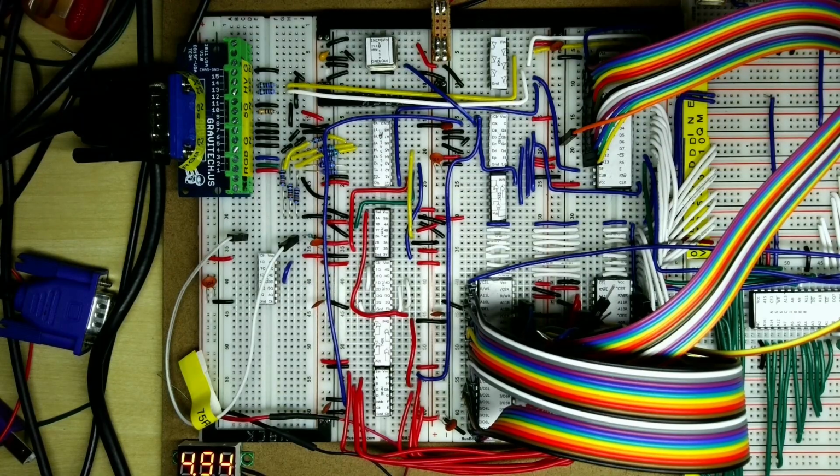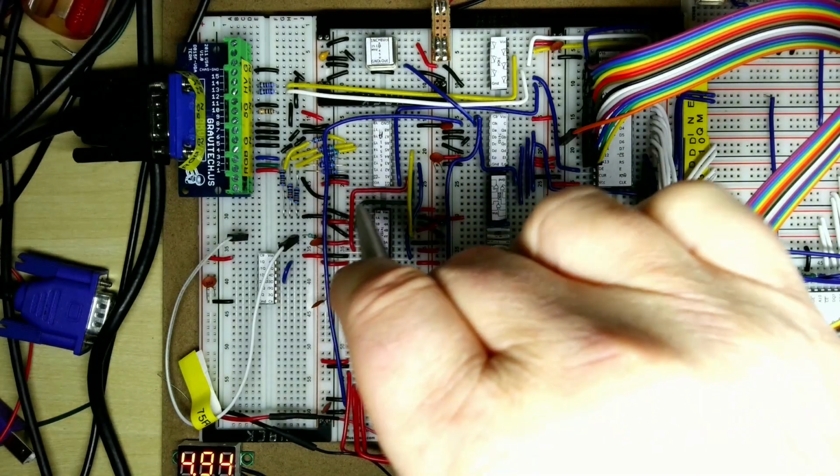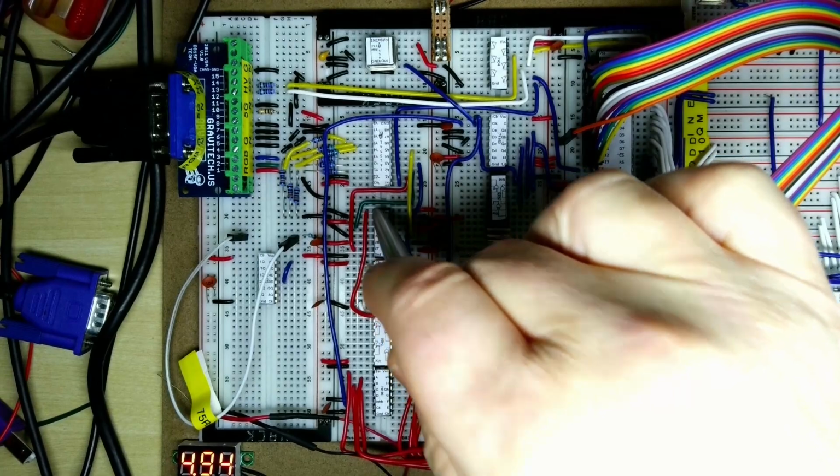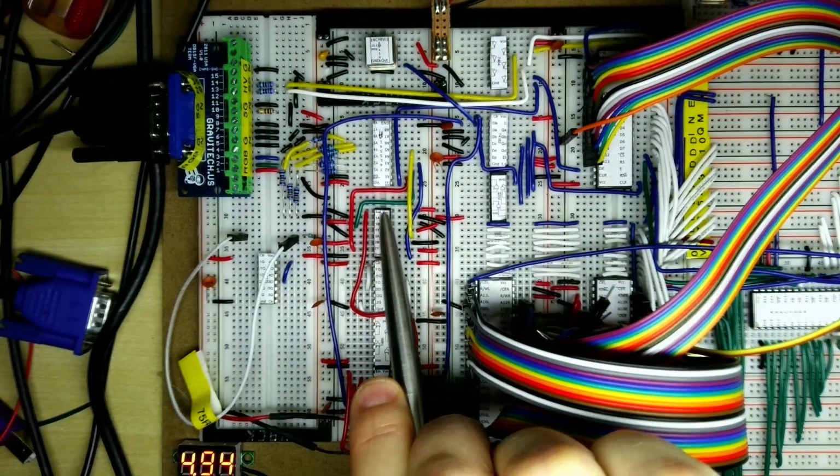So let's wire in the cursor. What we have to do first of all is, this is the output of the shift register, which has the serialized characters coming out as 1s and 0s, and at the moment I've just joined this at the top here off to the multiplexer input that determines whether we use the foreground or background colour.